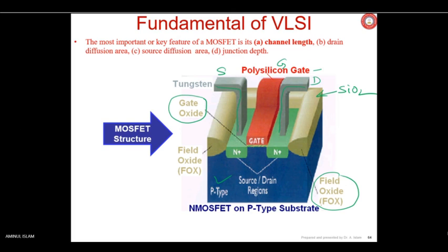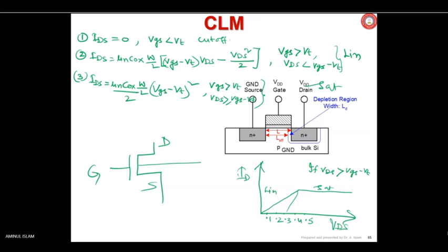Yes, I am going to use this symbol for the MOSFET, and you are also aware of the MOSFET symbol. Am I correct or not? Yes, sir. So normally, if it is a P MOSFET, it can be denoted as this, with source and drain. This is the gate. The bubble at the gate indicates that the charge carrier is hole instead of electron. If you don't have a bubble, as in the bottom figure, it is an N-type MOSFET. This is N MOSFET, this is P MOSFET.